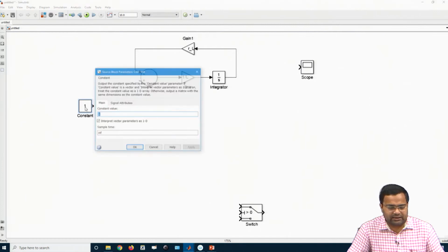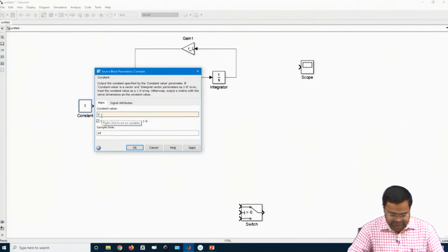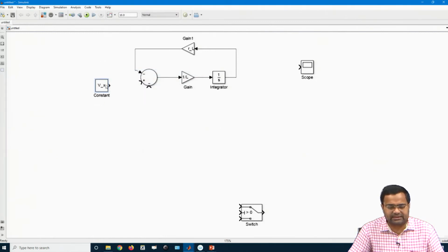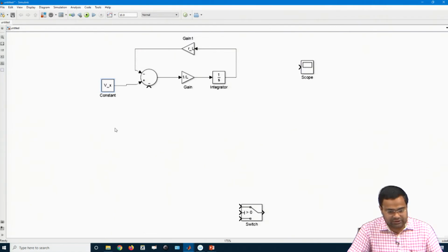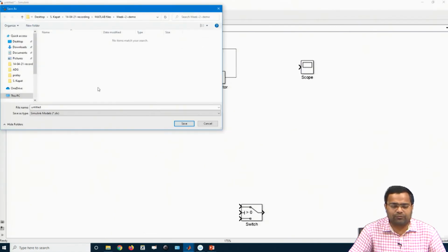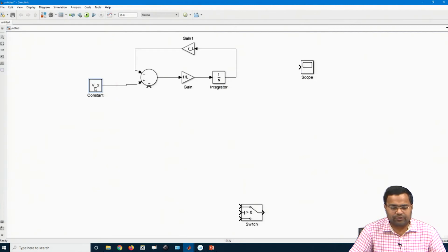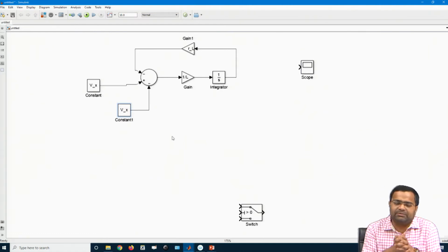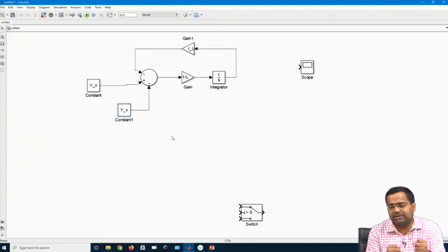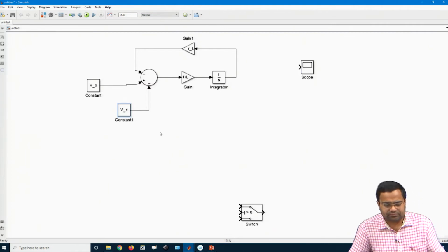So, this constant, let us say we define as Vx. Later on we will replace what is Vx. So, this Vx is added here, that is my switch node voltage, and then what else we need to consider is the output voltage. That means I need another input, the output voltage. This will create the dynamics of the inductor current, that means inductor current dynamics consist of these parts.